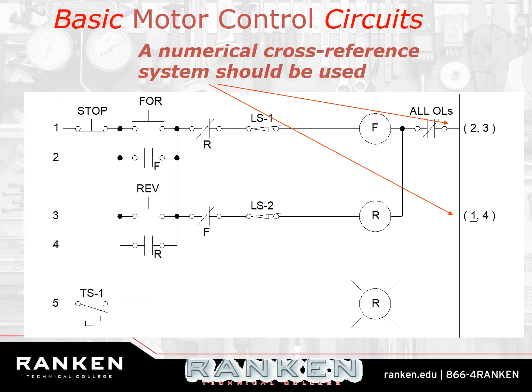The motor might be 500 feet away on the other side of the plant. I don't know if that motor turned on or not. But what I do know is that that closed and that opened. How can I tell that? Because I will have access to either side of those contacts, and I can measure them for voltage, or I can measure them for continuity.